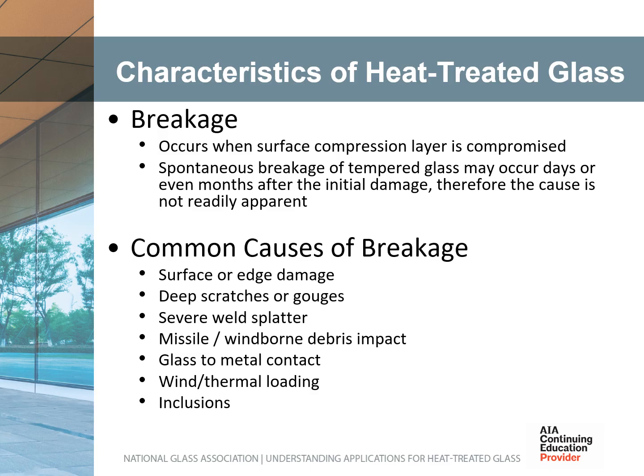And 7. Inclusions. In the manufacturing of float glass, impurities may be introduced into the molten glass. Most of these cause no particular problem. According to ASTM C1036, they are defined as a form of gaseous or crystalline or stone blemish. The specification offers test methods for detection as well as more information on size and frequency. In most cases, inclusions do not affect glass performance or cause glass breakage.